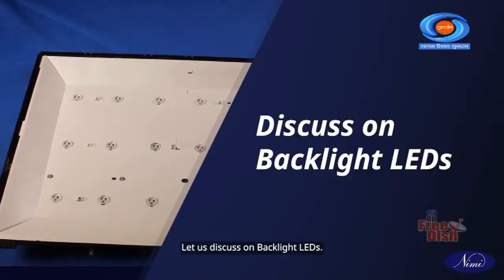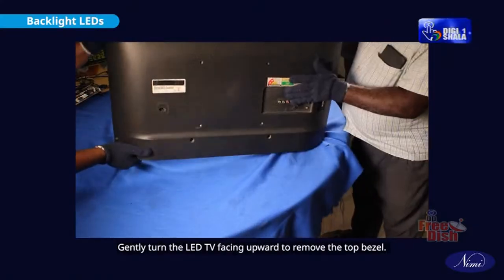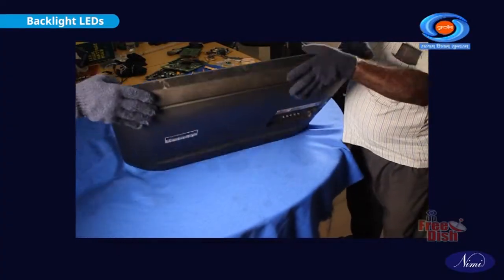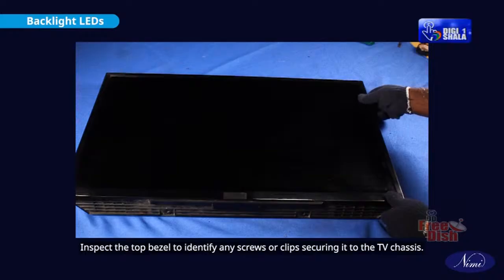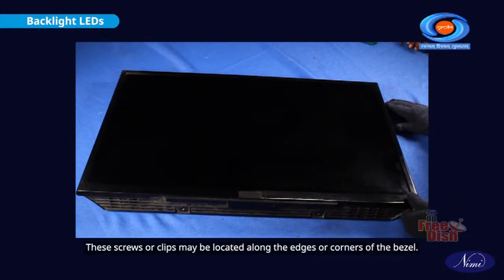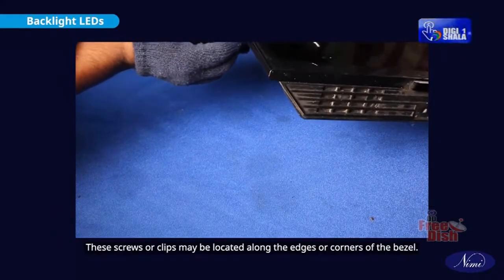Let us discuss backlight LEDs. Gently turn the LED TV facing upward to remove the top bezel. Inspect the top bezel to identify any screws or clips securing it to the TV chassis. These screws or clips may be located along the edges or corners of the bezel.